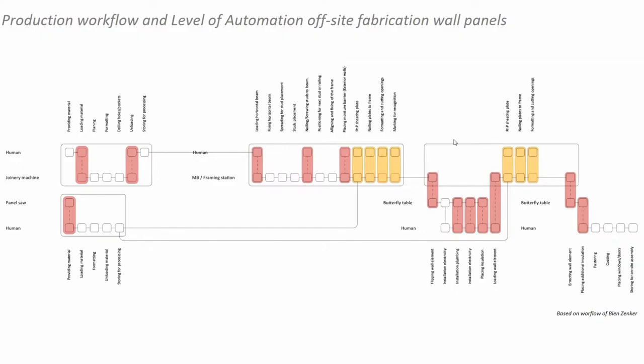And then the element is flipped again with this butterfly table as I was showing. Installation is placed, and the element is placed on the gantry system and lifted upright, and the finishing process, after the butterfly table flipped it and the second cover layer was placed, all these additional final steps are done to finish the wall.